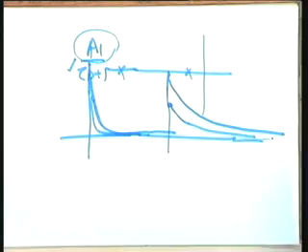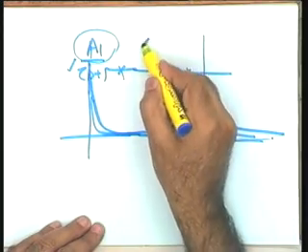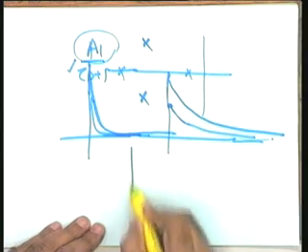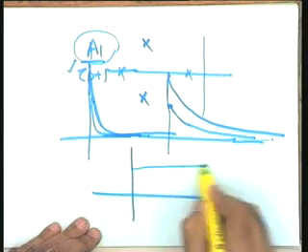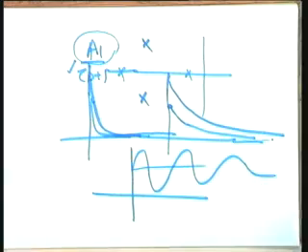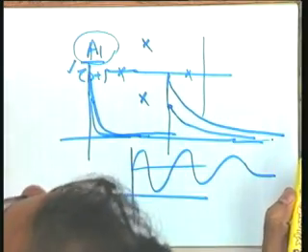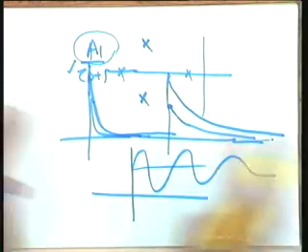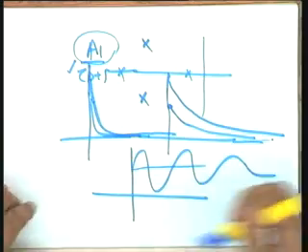But as far as the shape is concerned, whether the response is this way, now your poles may be this way. If your poles are this way, you know that your response will be oscillatory in nature. Damped oscillations or undamped oscillations. So it means the nature of the poles is going to guide the nature of the response. Now let us see how will the feedback action affect this.